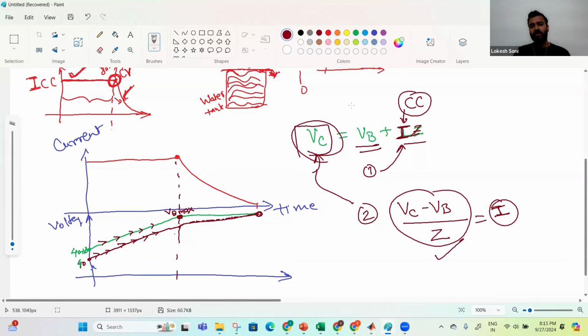So this is how CCCV works. Now people have, since I told that we have charging only as an opportunity where we can fully control the dynamics of battery, the behavior, the health of the battery. We try to use this opportunity to max. So boost charging, one of the charging things. Profiles which Vishal showed, where we pump more charge initially, that opportunity is considered because lithium plating doesn't happen much relatively at lower SOCs, right?